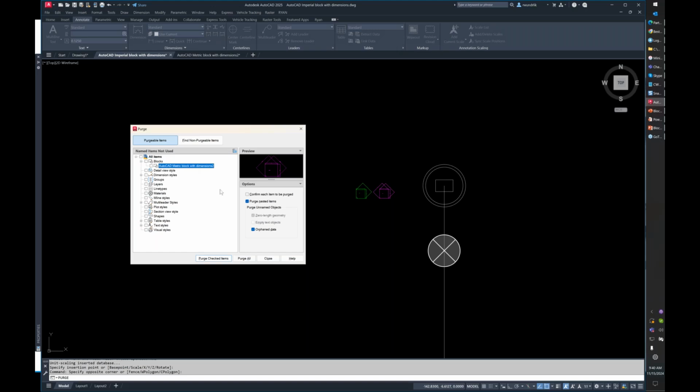I generally would not recommend exploding stuff in a drawing template unless you also plan on purging it, because that name will continue to live in the block definition. If you're talking about things like title blocks where you need specific information, you can explode that if you want. That would be a bigger discussion we need to have on exactly what it is that you're trying to get to.